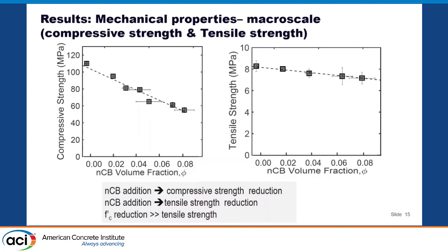I'm Konstantin Sobolev, University of Wisconsin-Milwaukee. Is this volume fraction of total volume, or is it silica fume replacement? This is silica fume replacement. What was the total silica fume content? Like 25%. So a very small portion of silica fume was replaced by nanocarbon black. You mentioned the particle sizes, but what is the morphology of the nanocarbon black? Is it porous material? Porous material.